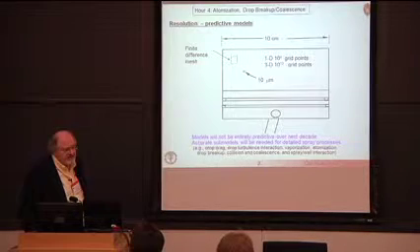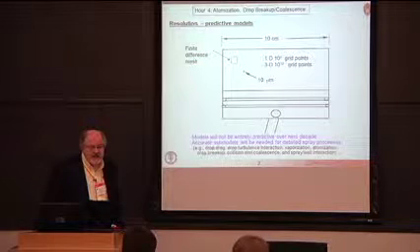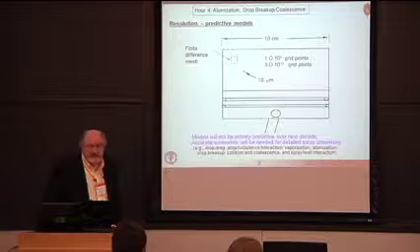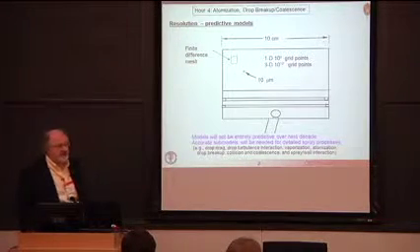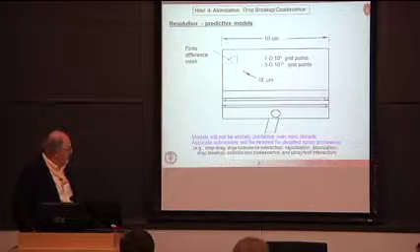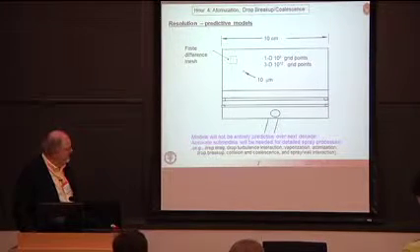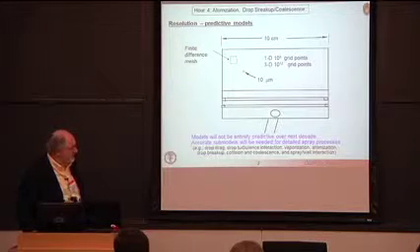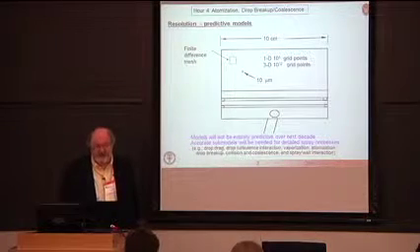And in fact, if you consider also boundary layer thicknesses in engines and various other things that we'll discuss later, we're not able to resolve those either with typical mesh resolution. So we need submodels for a lot of processes. And that's what I'm going to focus on this morning. So droplet processes such as drop drag, droplet turbulence interaction, vaporization, atomization, the breakup of drops, collision and coalescence, and spray wall interaction are all things that are going to be modeled rather than resolved.